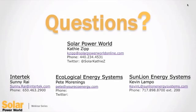it's provided the proper grounding connections, because those of you who've been in the industry for a while know most of the accidents to date in the industry are related to failure of grounding one way or the other, and there are a couple of major fires that have taken place. So most of the city and county inspectors are very particular about making sure the systems are grounded properly. So if it's attached to a module, you're looking at meeting AC module requirements. If it's attached only to the railing, then you're looking more along the lines of only grounding requirements and not so much of the module requirements.